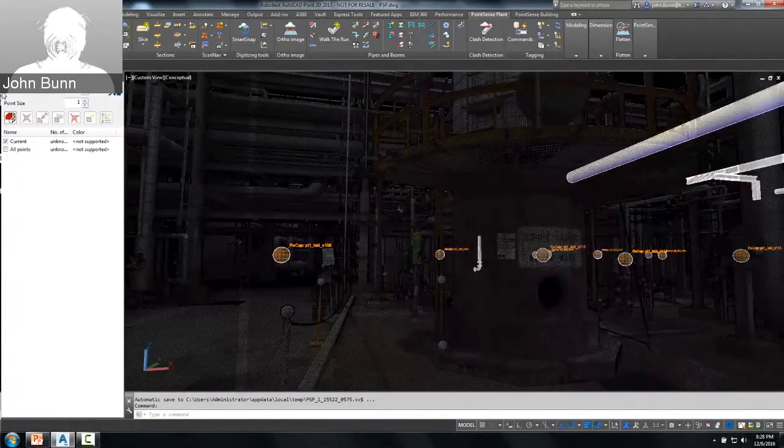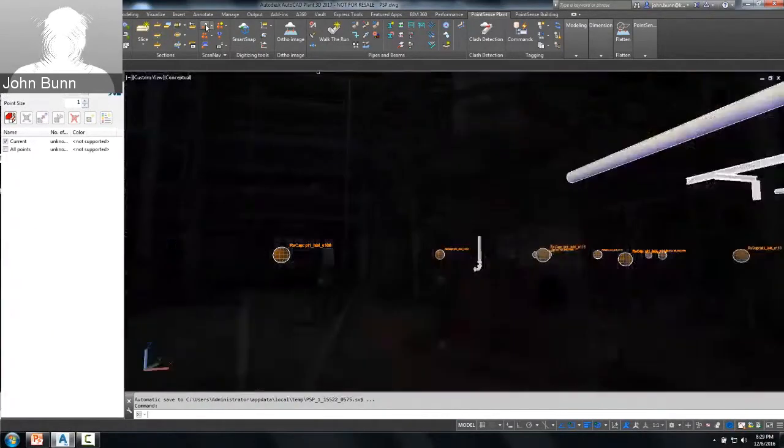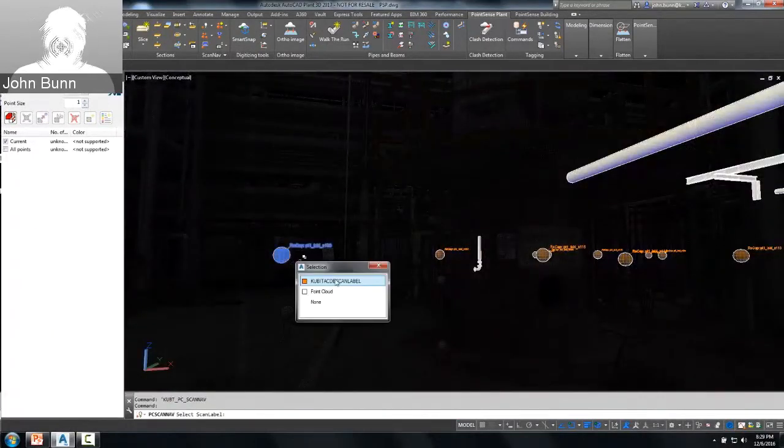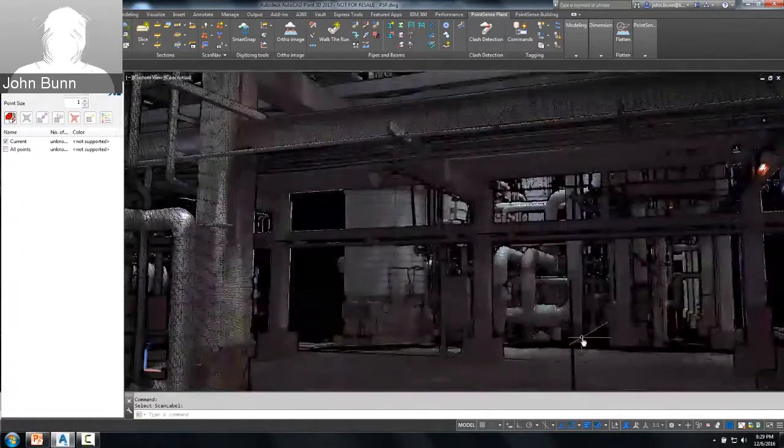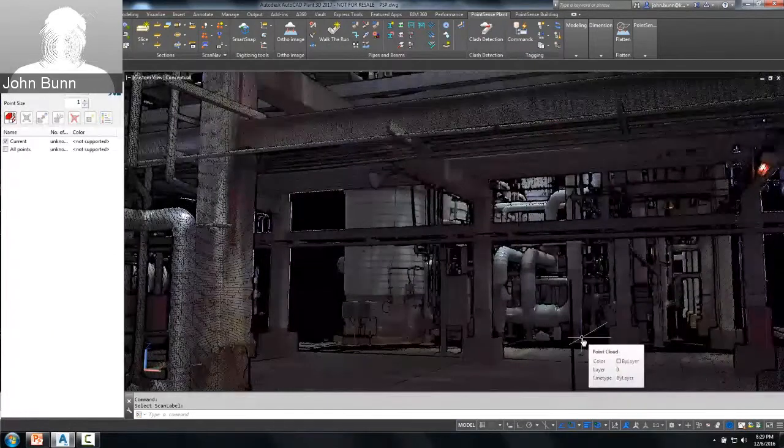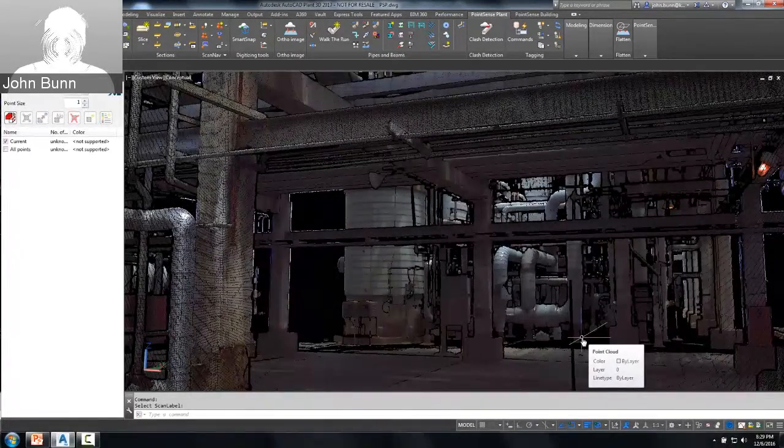But it helps to find where you're at and find out what you've modeled. Now, what we've also done is when you click the scan navigation button, we also do a transparency. This is so you can see those spheres easier, and so you can actually highlight them through the point cloud. I'm sure everyone who's done scan navigation has come across the problem where you can't see the sphere through the point cloud. So that's a very nice feature to help users move around more quickly and without having to turn the point cloud off completely.